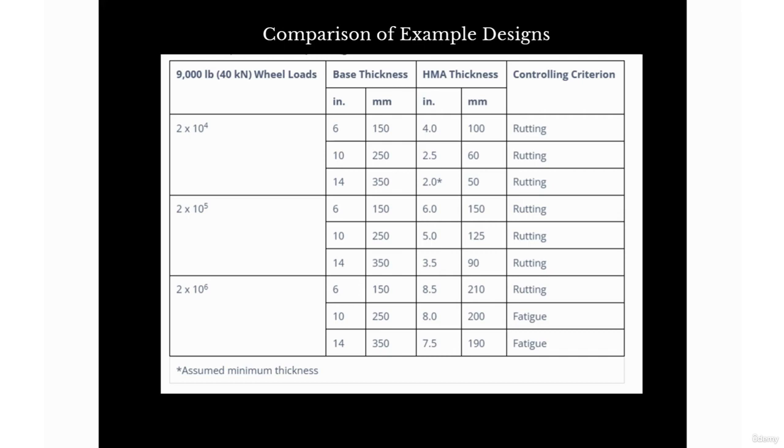So instead of having a 350 mil thick gravel layer, you'd maybe make it 200, or 250, and then your asphalt doesn't have to be as thick. You try and manage your asphalt thickness. You mix and match, in a sense. But if you have more aggregate, and it's cheaper and it's available, most definitely you can go for it.